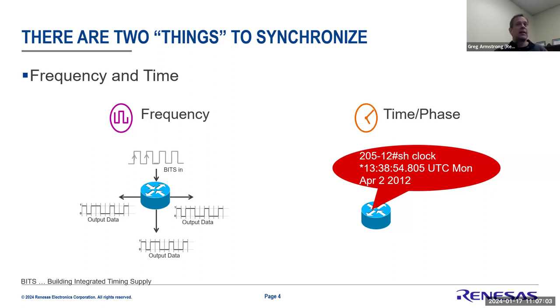And then again, time is just putting a label onto that. So a pulse per second happens every second, but you want to have some starting point of that counter to be at what we call epoch time or time zero, to say how long has it been since the first time count started?